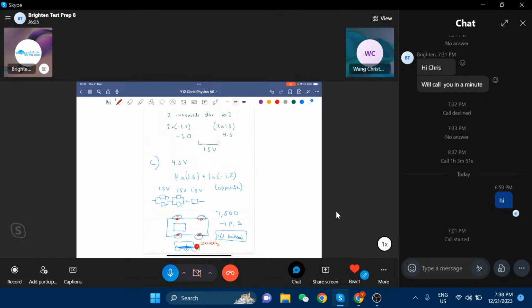You have very short ways, right? They have the momentum from the electric motor go straight to the wheel with no big difference. You don't need a long shaft. If you compare it to the, now I should have made that in green, actually, not to confuse it with the engine. Whereas if you have the engine here in the car, then you need a transmission, and if you have a 4-wheel drive, even worse. Then you have a transmission very long all the way to the back. Then it goes out to the axles here, and then you drive them. So you can imagine the weight of the so-called drivetrain.